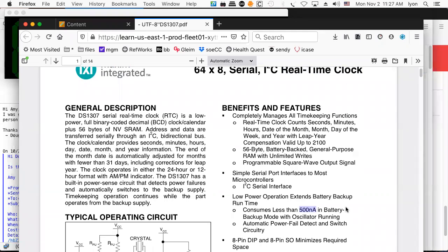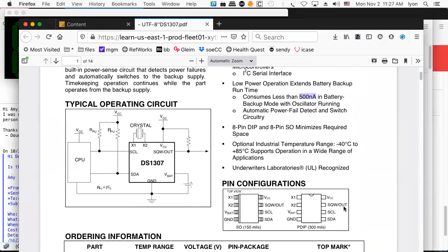So what's going on here is you take a little quartz crystal and you add it to the chip. That's kind of an unfortunate thing you have to do because it means you have to add stuff. And when you add that crystal, what you're adding is something that vibrates at a frequency of 32,768 hertz, which happens to be the same frequency that you would find in a common quartz watch. So basically, you're putting in a chip with quartz watch accuracy.